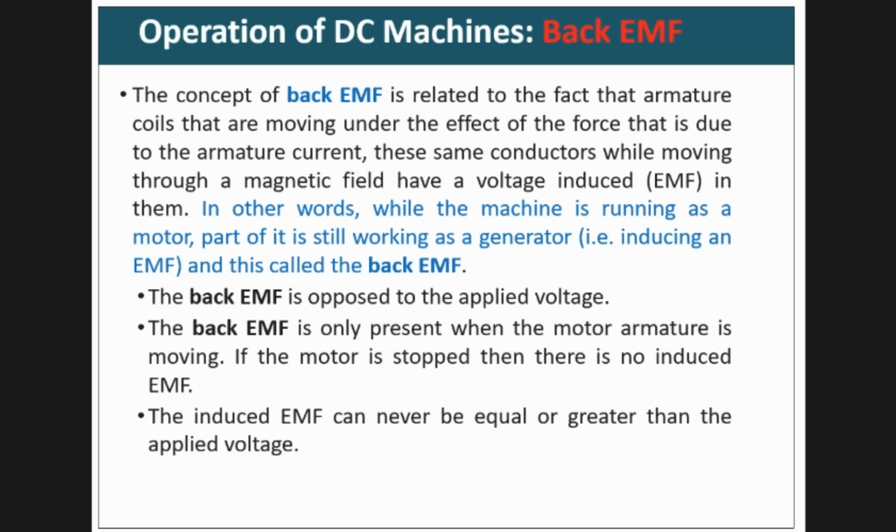So in this slide I am going to explain about the back EMF. This is mainly related to the motors. The concept of back EMF is related to the fact that armature coils that are moving under the effect of force that is due to armature current, the same conductors while moving through a magnetic field have a voltage induced, that is called the back EMF, in them.